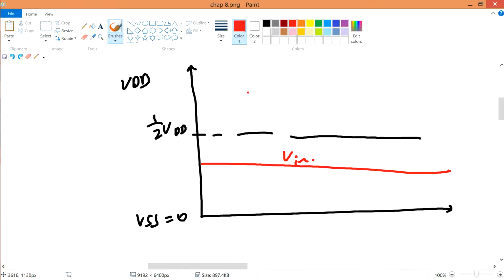If you take a 4-bit system, the first bit will determine whether your V-in is lower than half VDD or not. The first bit talks about half VDD, while the second bit talks about 1/4 VDD, and then 3/8 VDD, etc. But I'll just continue first so you get the meaning of that. At first, it determines whether it is lower than half VDD. If it's lower, then it's a 0 bit. If it's higher, then it's a 1 bit. You get what I mean?